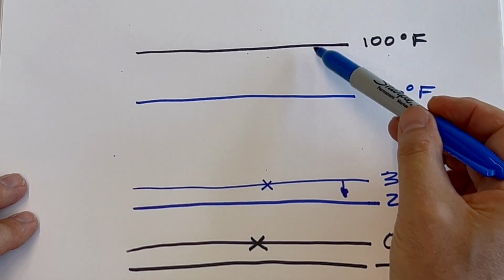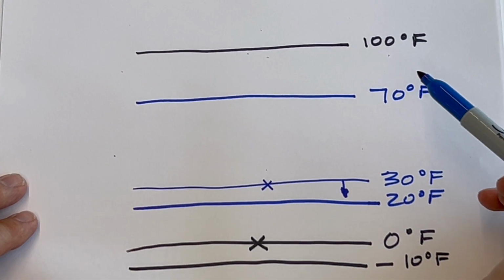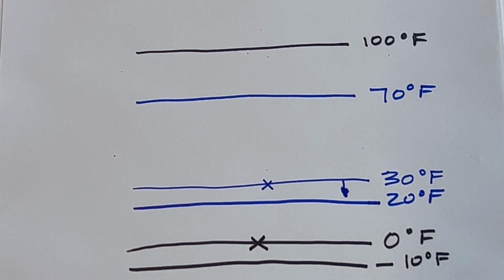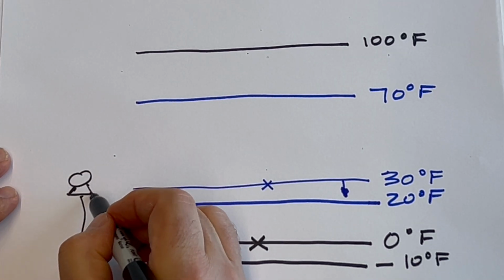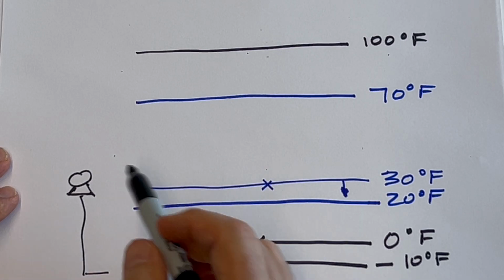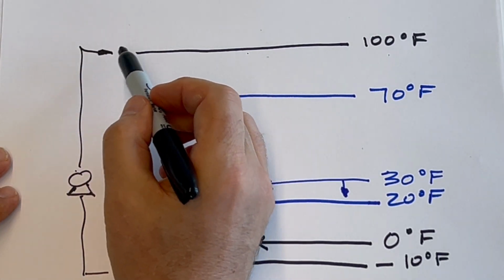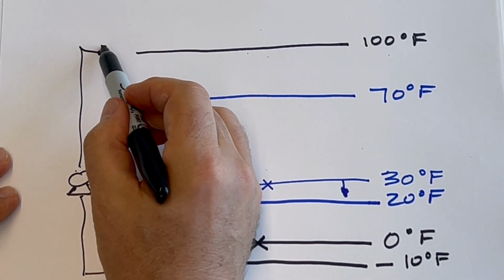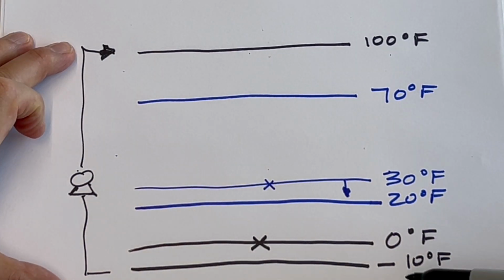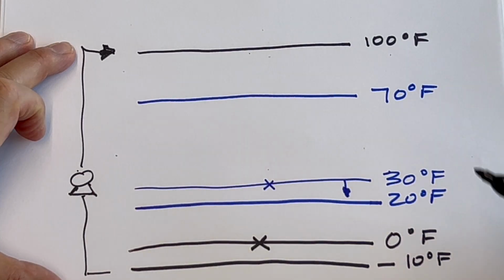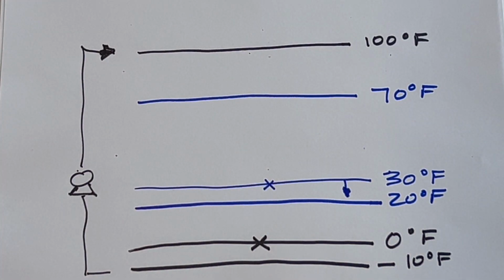There might be a minor change up here, but not much. The key here is that now the compressor, which is compressing from the low temperature and pressure up to this high temperature and pressure, is going to have to work harder because it's compressing over a bigger temperature change.